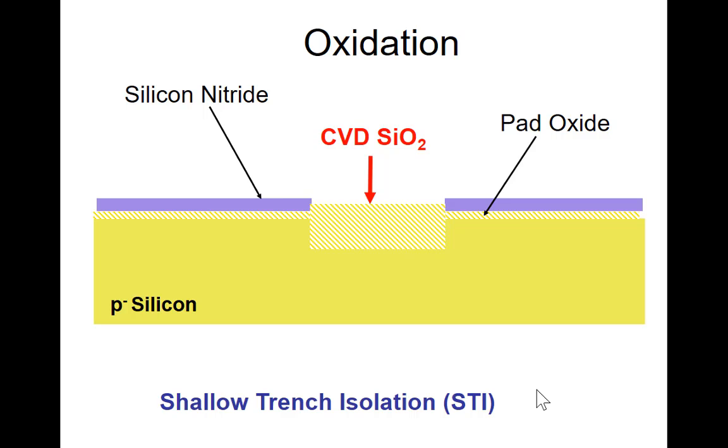Then you are going to have a p-n junction depletion region, and that depletion region can be much wider than the shallow trench width. It can be 10 times wider. So then your area utilization is not good. It's all wasted on these p-n junctions between the P materials and N materials.